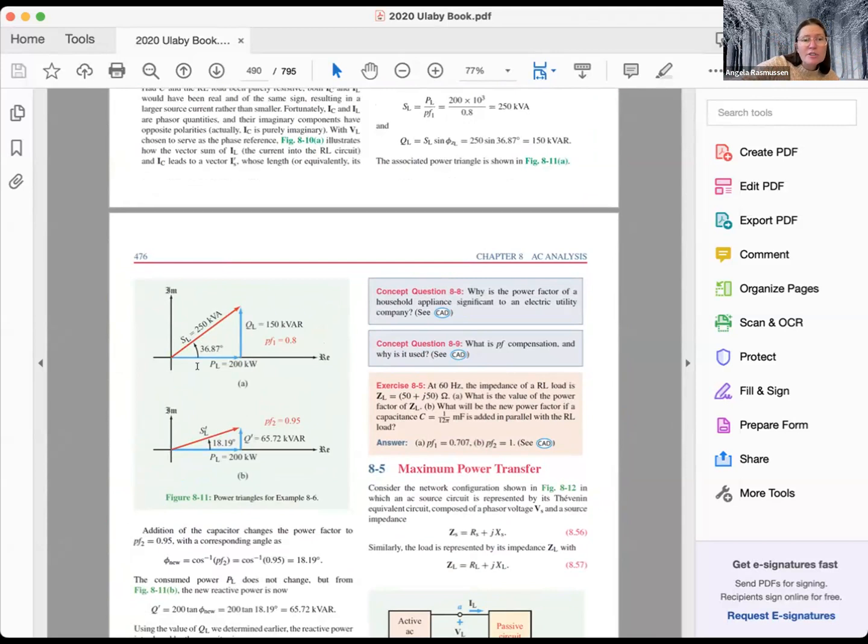And so most of the time we want to eliminate those effects. You may measure what the full system does, knowing what your circuitry should do, and then shift the phases by adding an extra capacitor or an inductor to remove and minimize that effect.